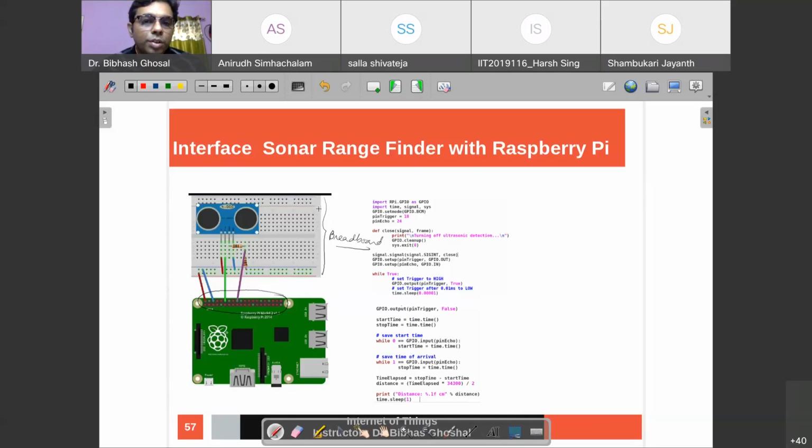So these vertical holes are internally connected, one column. If you connect any wire to this hole, all the holes will have the same connection. It means connecting to all the holes. Any wire connected to one hole of one column means connecting to all the rest of the holes. Not this one, these are two separate. These two are separate.